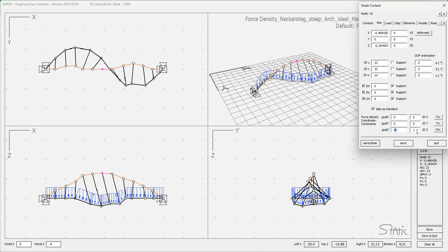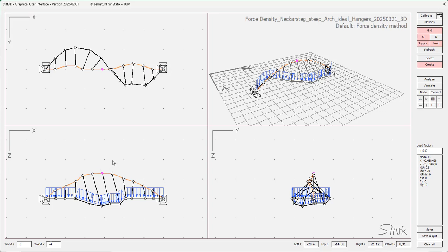Here we can give in any numbers you like. They need not be in sequential order. They are simply tags, so we can refer to the respective constraint. So we save it, and now observe my cursor here. You see that z equal to -4 and z equal to -8 would be somewhere up there. So that's where we'd like to lift the arch while form finding.